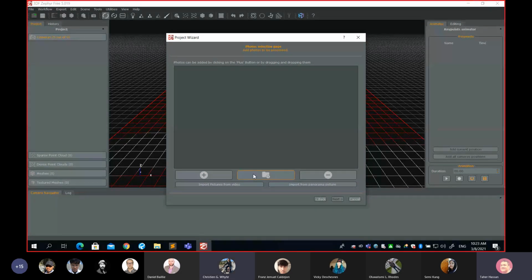Well, if you're using this version, you can only use 50, right? So you'd have to add the images individually. Exactly, sir. That's exactly my point, or the trick. If you add a folder that contains more than 50 images, the software will complain. If your folder has less than 50 images, which is our case, the wooden mask, then I can simply add the folder and it will grab all the photos in that folder. Okay, you get the idea.